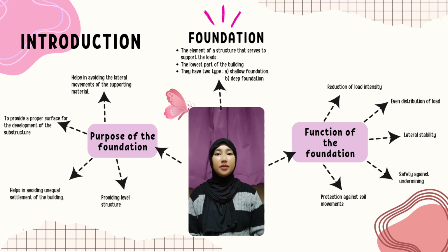Foundation is the element of a structure that serves to support the load, and it is the lowest part of the building or the civil structure that is in direct contact with the soil, which transfers load from the structure to the soil safely. Generally, the foundation can be classified into two, namely shallow foundation and deep foundation. A shallow foundation transfers the load to a stratum present at a shallow depth. The deep foundation transfers the load to a deeper depth below the ground surface.